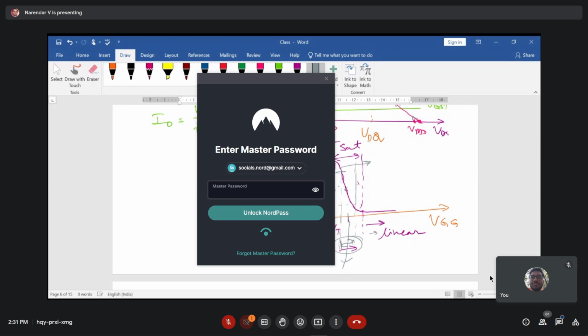When it is above VT, the transistor goes into saturation, and there is maximum amplification for your transistor. Okay, so what you basically require is biasing in such a way that, let's say here it is 0 voltage, that is referred to as your biasing, where VG is exactly at 0, and then you are applying an analog signal here, and you have a threshold voltage of the transistor, let's say it is here.